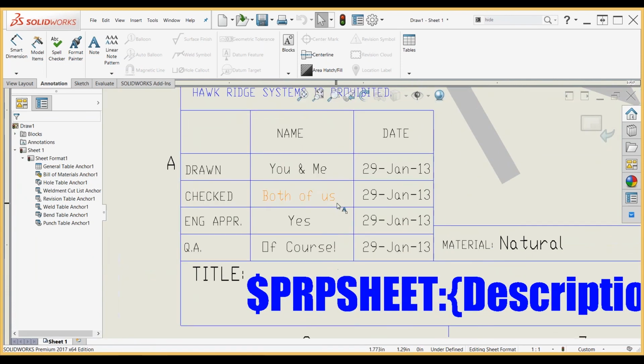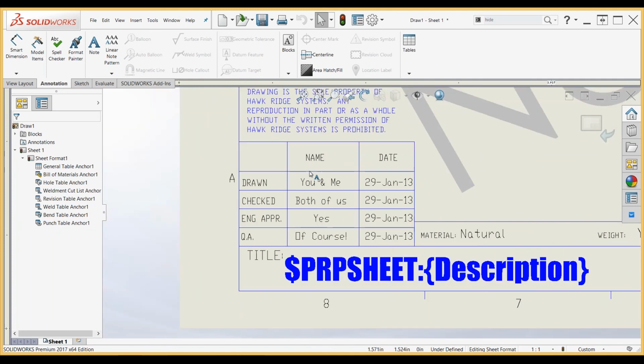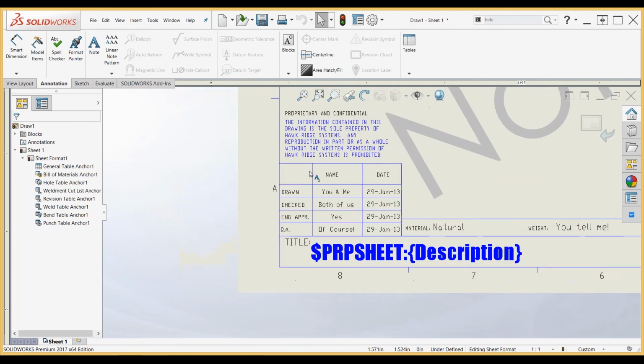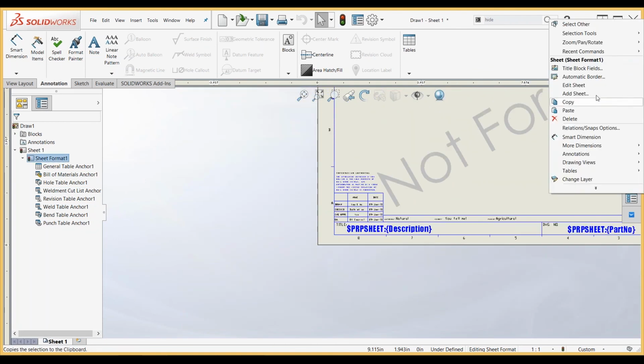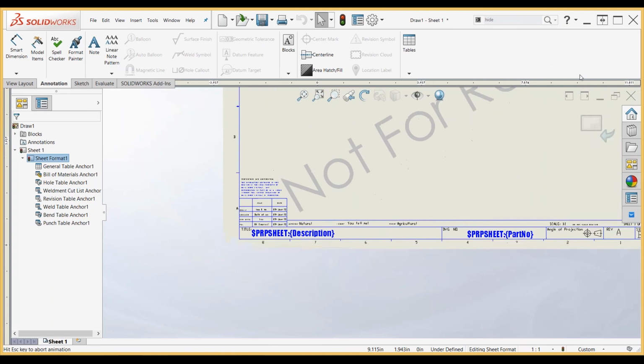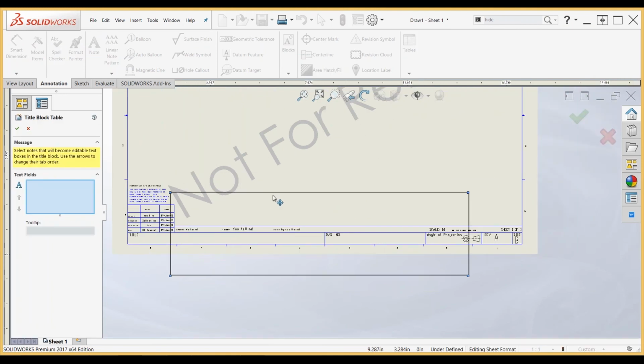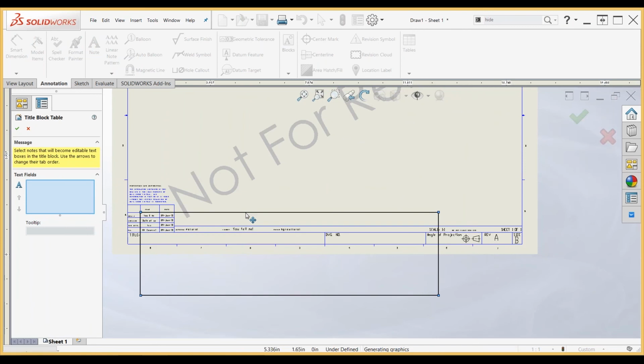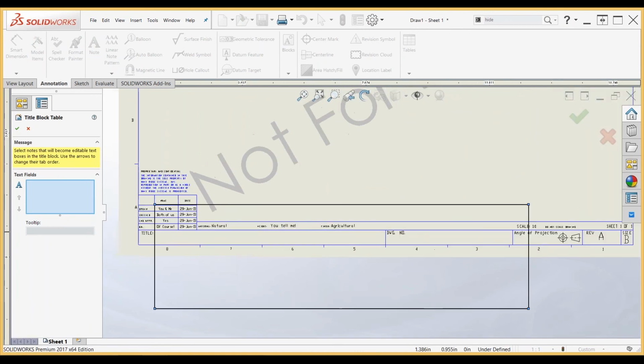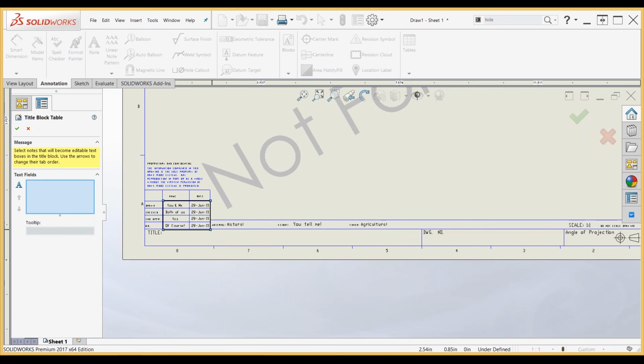I'm going to go up a level, so I can't grab any of my formatting. This is where you'd start throwing down views and stuff. But if you come to the title block and put your mouse over it, you see this nice little dashed line appear. And if I double click, I can now start editing all of this information. Of course, pushing the Tab button will toggle through them, and Shift Tab will toggle through them in the reverse direction. So I don't know how good your feedback is of me spamming through my Tab button, but Tab will toggle through them, Shift Tab will toggle backwards.